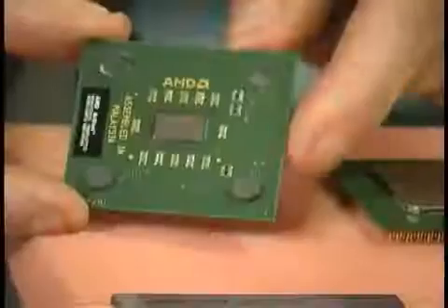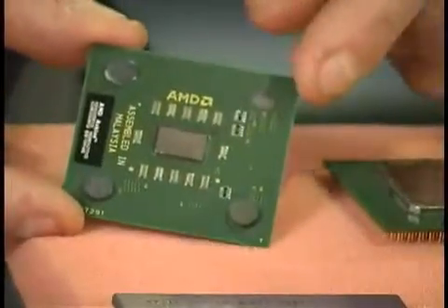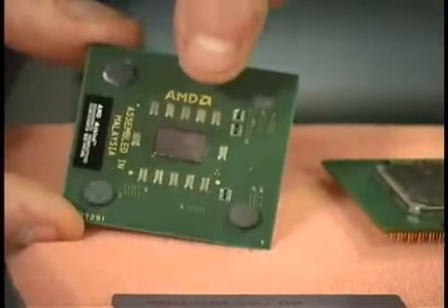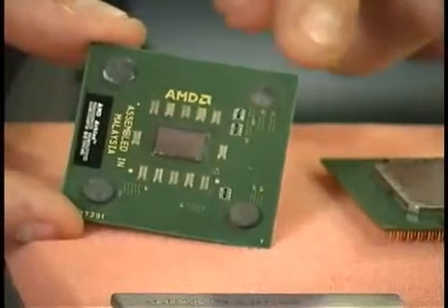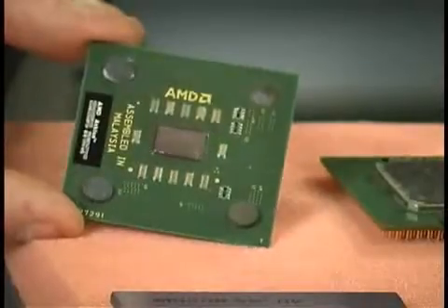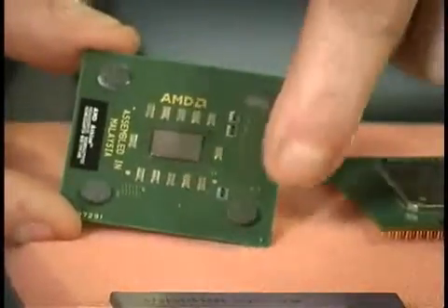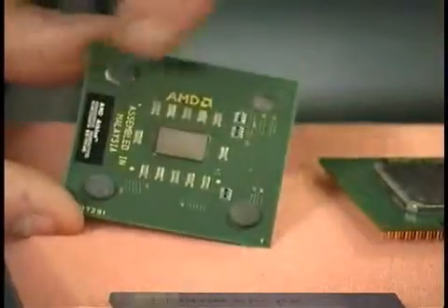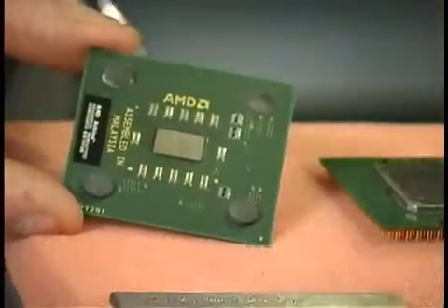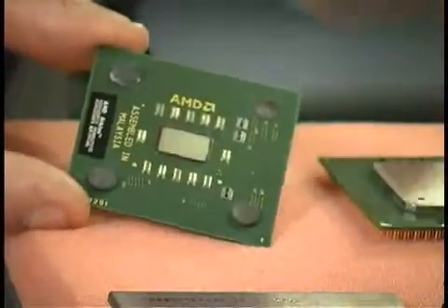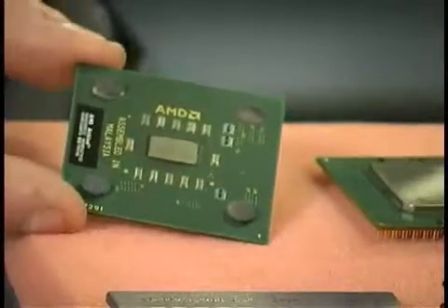So what would happen was when you would put a heatsink on a chip like that, and here's an example from AMD. This is an AMD Athlon processor with the raw processor die sitting right in the middle of the chip there. If you put pressure on it, it would crack the die. What AMD did was put rubber pads around each of the four corners to try to mitigate that problem, but still it was happening all too frequently.